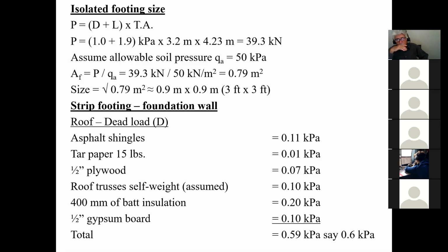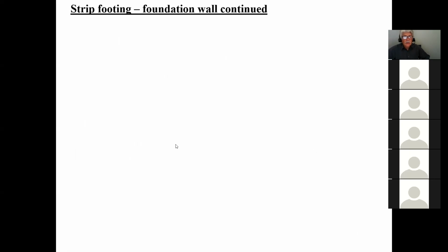Okay. Now, after that, what other load are we going to have on the roof? Maybe the gutters. Snow. Okay, snow. Good. So the other thing that we're going to have on the roof is a snow load. And we've calculated the snow load in our steel, right? To be 2.5 kPa, if I'm not mistaken.